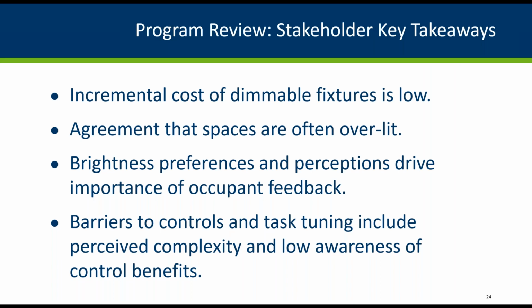Our interviews with program stakeholders included manufacturers, energy efficiency consultants, electrical contractors, and lighting sales representatives. Key takeaways from these interviews include feedback that major lighting manufacturers have LED products capable of task tuning today, and that the incremental cost is small to none for dimming capable fixtures compared to code required controls. Generally, these stakeholders see overlighting as an issue, and the conversion to LED lighting creates spaces that could be task tuned to 75 to 80% of designed light levels.